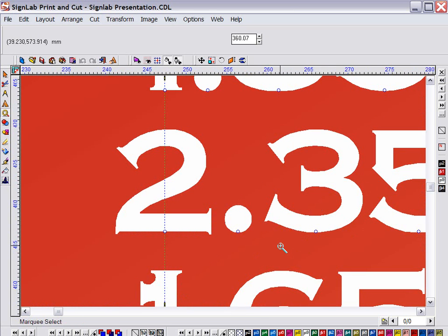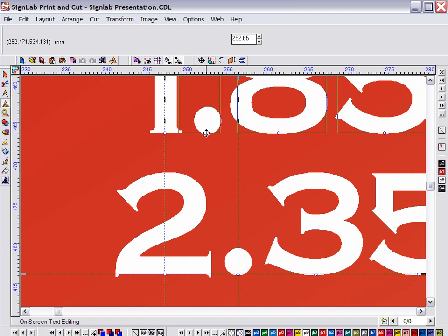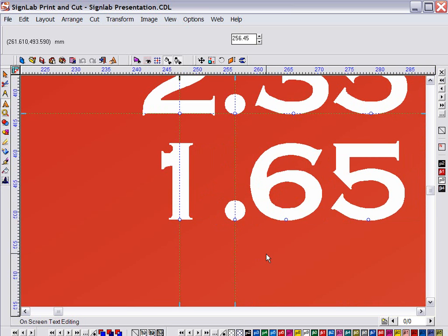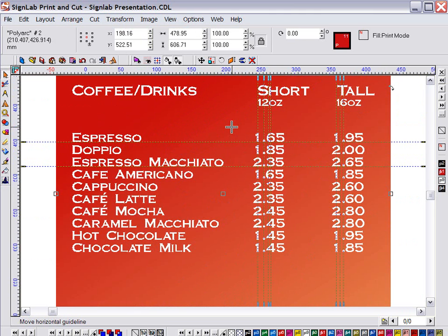Now take a look at this decimal. I'm happy with its position and want to bring all the other points in line with it. If I press the control key and right mouse click on that point, I can place a guide directly through its location. Now all the other points can be brought in line. I can summon as many guides as I like to make this task unproblematic and easy to do. When I'm done, I can simply hit the shortcut to remove all guides, and the job is done.